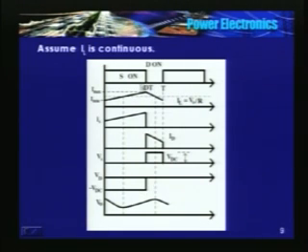You might have turned off the switch at this point. Once you turn off the switch, current starts decreasing, but this inductor current is higher than the load current till here. So, in this period, the capacitor charges. Please do not say that the capacitor starts charging at this point and stops charging at this point.